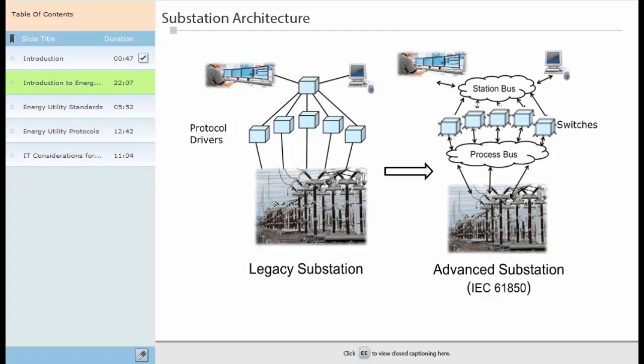When comparing the legacy to the advanced substation, several facts should be noted. In the legacy substations, devices communicate through a combination of rigid wiring and low-speed serial communications. Intelligent electronic devices within the system transmit data through wires connected by output and input ports. The system is inflexible, impractical, and limited in its scope of control. In many cases, communications between intelligent electronic devices are not feasible.